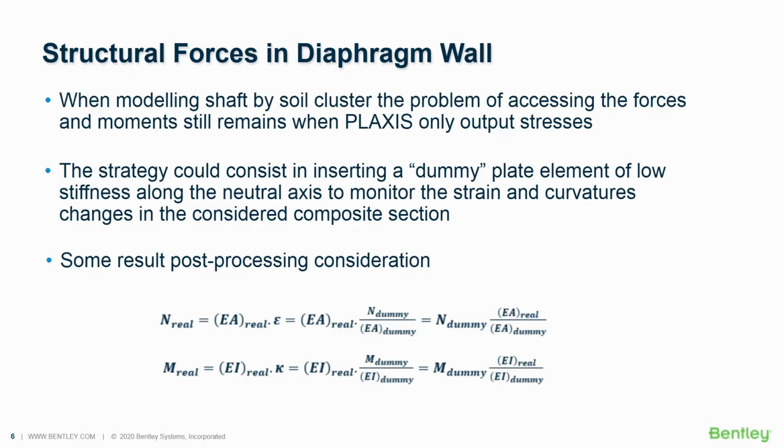So here there would be 2 strategies that could be used. I am just here talking about one, but I should also mention that now in Plaxis 2D output, it is possible to automatically calculate the structural forces resulting from the integration of the stresses in such a retaining wall by using the automatic center line. Maybe some of you are already aware of that. It computes along that automatically detected center line for the selected soil clusters. In that case, that would only be the retaining wall cluster, to compute the integration of the stresses and calculate the resulting axial forces, shear forces, and bending moment.